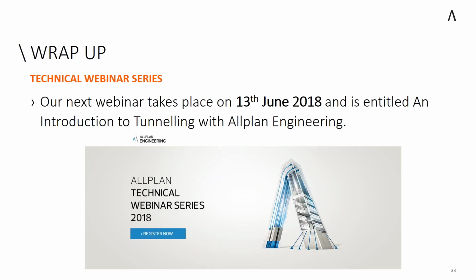However, recognizing that laser scans create lots of points in a very small area, I would say that for certain applications, it is going to be far too much information from an initial design perspective, or what Allplan can do at the moment. If those point clouds were decimated, so that we're no longer talking about 10 mil intervals, but 100 or 500 or even 1,000 millimeter intervals, then again, it's going to be a lot easier for Allplan to handle that amount of information at the moment.